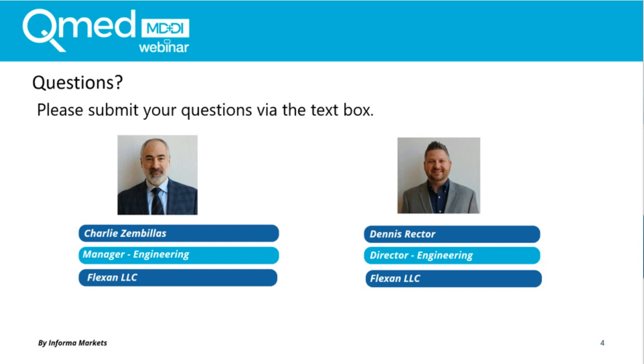And we'll move on to another question here. What are the typical tolerances that can be achieved in silicone extrusions? So generally, the tolerance would depend, obviously, on the size of the extrusion. Generally, as a good rule of thumb, if you could do plus or minus 1% of whatever size you're looking at, that's typically the tolerances that we are meeting and validating to. All right, thank you, Dennis.